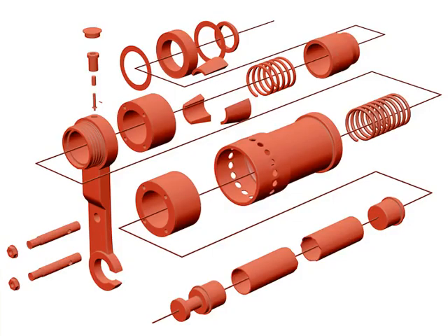Exploded assembly drawings are not very common in a set of production drawings. They are best utilized to show both the individual pieces of the assembly as well as the order in which they are assembled. Exploded assembly drawings are typically used in maintenance manuals, parts catalogs, or other information given to the general public. With the advent of computer-aided design, or CAD, it has become easier than ever to generate exploded view drawings. A full set of production drawings may contain detail, assembly, subassembly, working assembly, and diagram drawings that are all used to depict the final product.